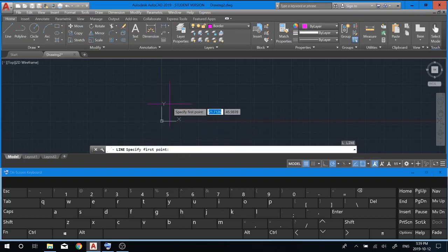So to specify the first point, I have to put in the X and Y coordinates, similar to what we did with limits. So I'm actually physically going to type 0, jump over to that second box, which is comma, right? Or tab. So I'll use comma, 0. And then I can hit spacebar.